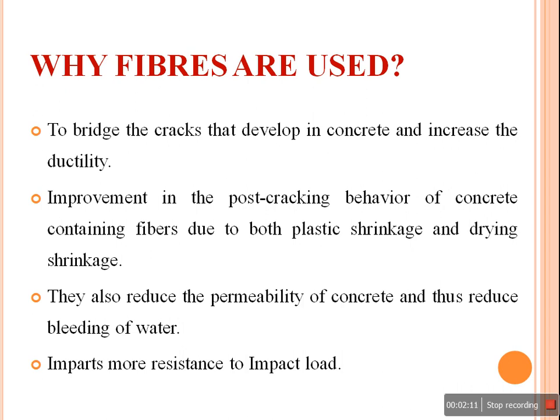So the main idea of these fibers is to bridge such microcracks that develop in the concrete and increase the ductility of the concrete. There is an improvement in the post-cracking behavior of concrete containing fibers, due to both plastic shrinkage and drying shrinkage.